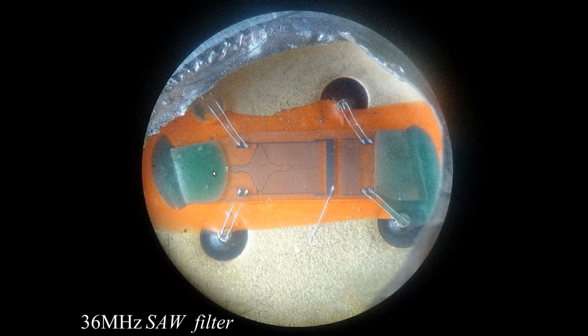It's 3 dB for this absorber, 3 dB for this absorber. Further, the loss in the lithium niobate, the insertion loss of this filter, is usually above 10 dB, usually 15 dB, even up to 20 dB. But this was a cheap solution for analog television receivers.